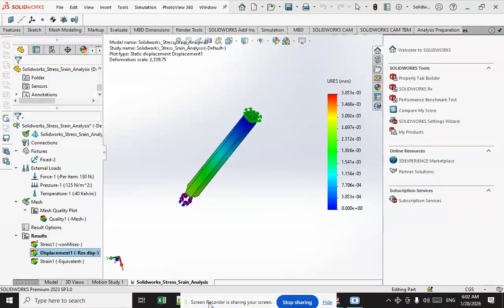The stress or load or deflection the structure is expected to experience is known as the working, the design, or limit stress. The limit stress, for example, is chosen to be some fraction of the yield strength of the material from which the structure is made. The ratio of the ultimate strength of the material to the allowable stress is defined as a factor of safety against ultimate failure.